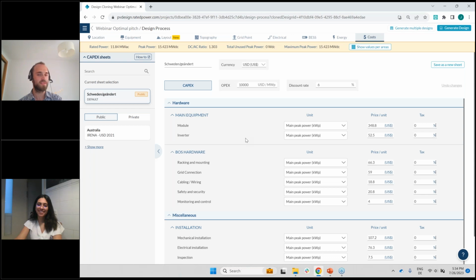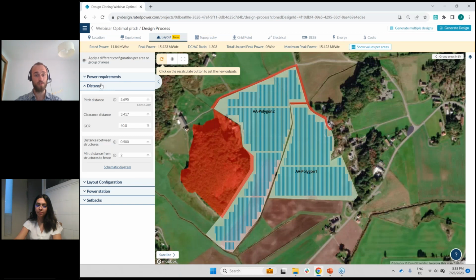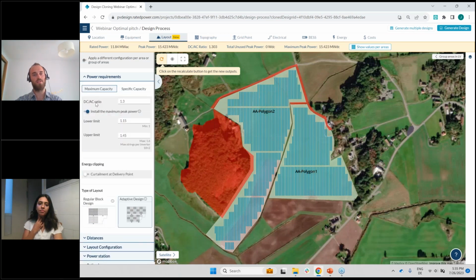Maybe Ghada, can you repeat the second part of the question? It was related to DC-AC ratio, right? Yes, it was asking, and does the performance ratio value depend on the DC-AC ratio? Yeah, the performance ratio does not depend on the DC-AC ratio. So DC-AC ratio, I can just jump here. It's a layout tab. You can have an overview in the power requirement section here. This is where you can define the DC-AC ratio. In this case, we defined 1.3 as our goal, and we allowed the software to connect our inverters in a little more flexible way.